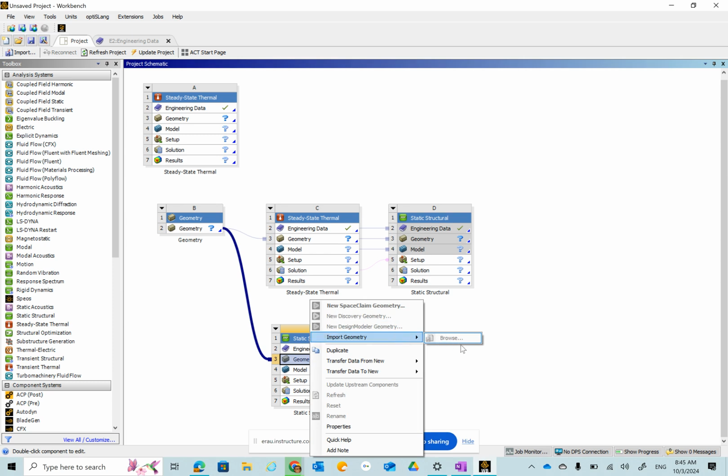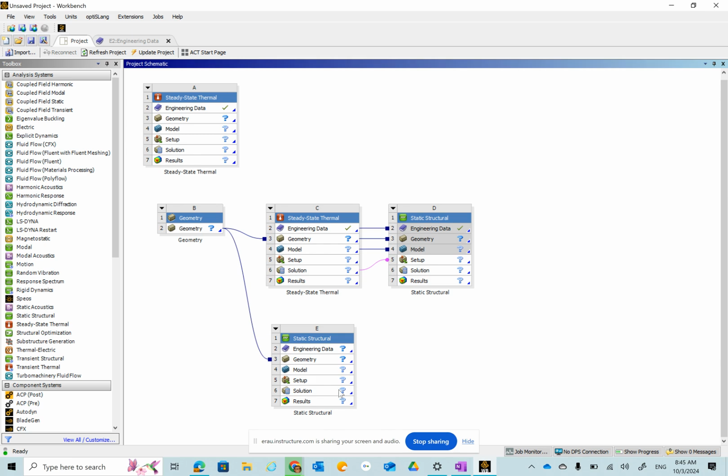So it looks like this is not enabled here, but I should be able to create a geometry, import a geometry from CATIA, from Creo, from SolidWorks, a STEP file, IGES, you name it. For the model itself, if you double click on model, as you can read here, it says starting Mechanical. So this is going to launch another interface, which is ANSYS Mechanical.